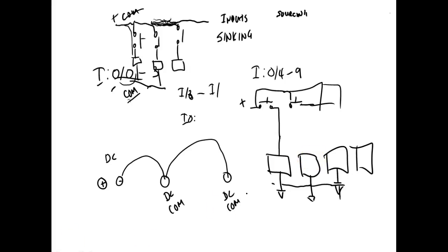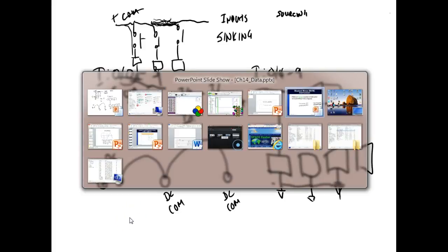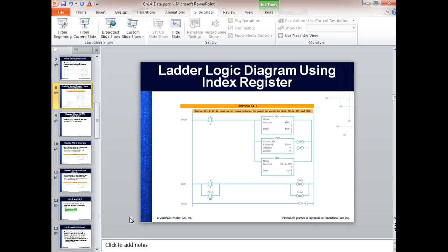Yeah. Them kids got there, they had no idea what a circuit was. They knew a schematic, but they didn't know what a circuit was. And so when you get in here and actually physically see these things wired up, drawing those connections on a little diagram is not the same. And you really, really need to understand sinking and sourcing, because if you get into a plant that's fairly new, they're going to use DC inputs. They might use AC output, but they're going to use DC input. I know that's kind of off the subject matter, but that's very, very important.